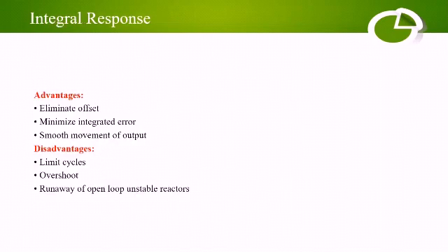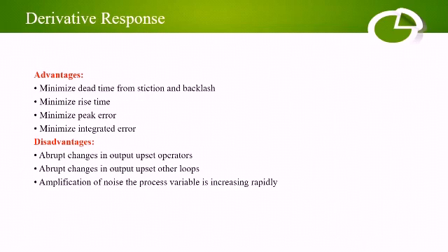Integral response. The integral component sums the error over time. The advantages are that it eliminates offset, minimizes integrated error, and gives smooth movement of output. The disadvantages: limit cycles, overshoot, and runaway of open loop unstable reactors.